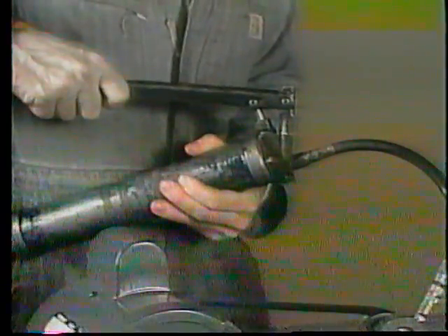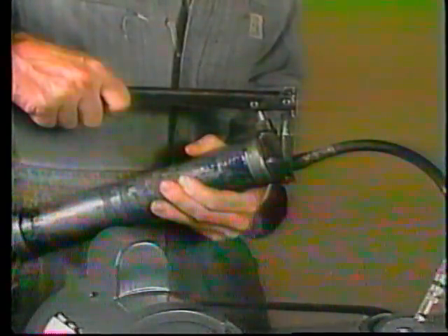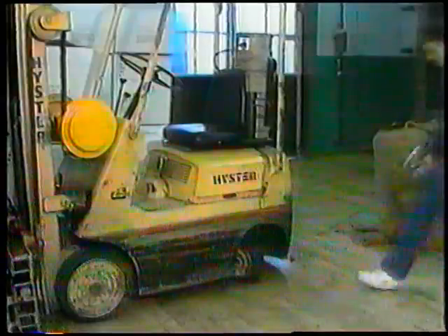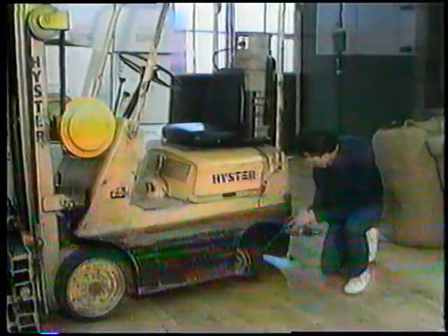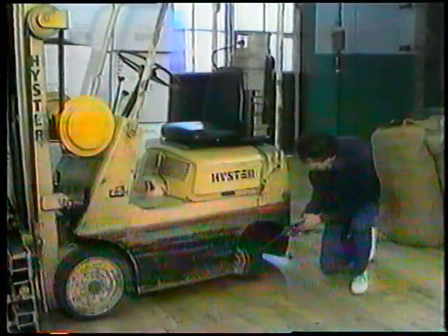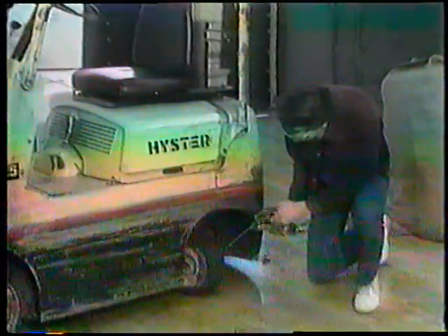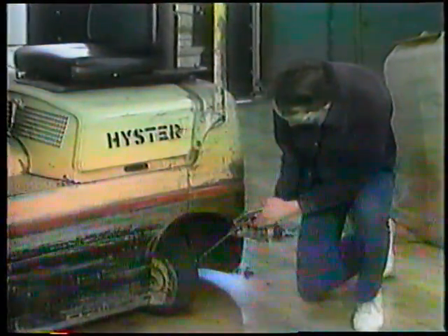Pay attention to the feel of the grease gun. If it pumps easily at first, then stiffens up after a few shots, stop. The bearing is probably full. In the case of a rolling element bearing, remove the grease nipple temporarily and allow the bearing to purge itself while the shaft turns. You may also find rubber shields or boots on some kinds of joints. Some will allow grease to vent, some will not. If you see the boot swelling as you add grease and no old grease comes out, stop.